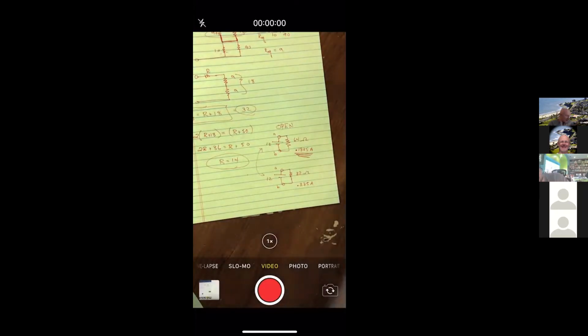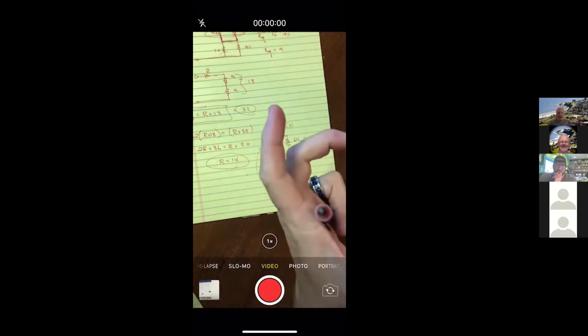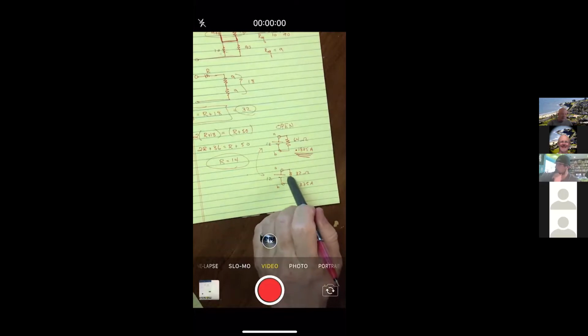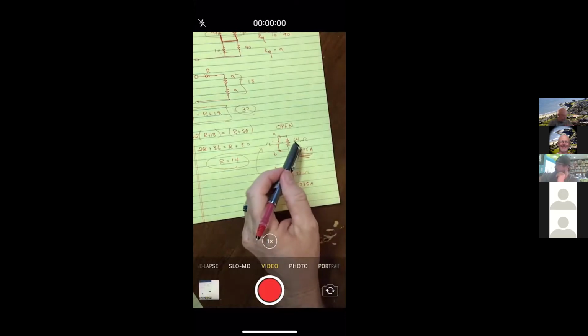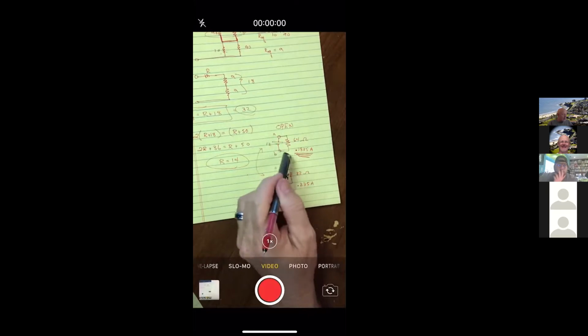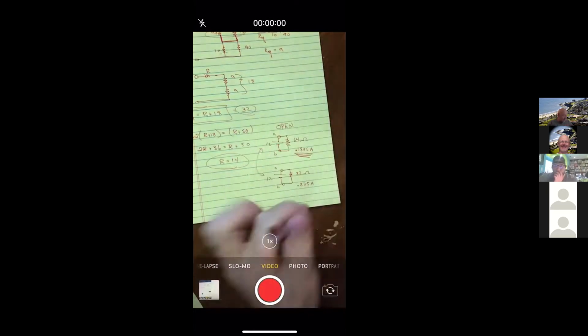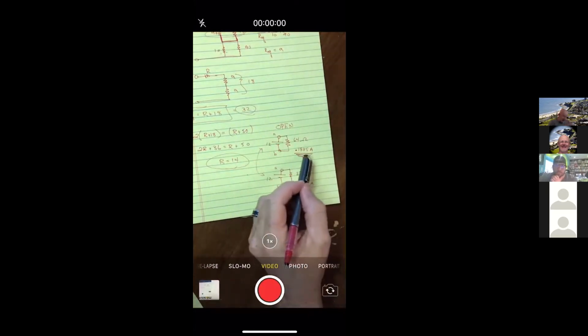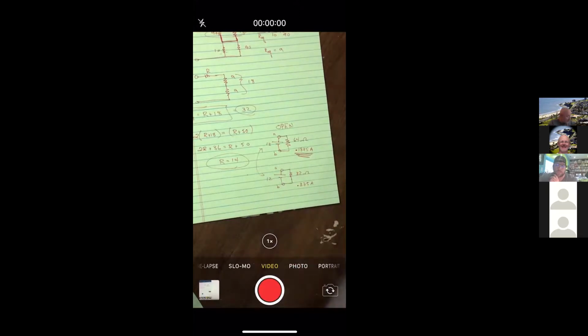But then when nighttime comes along, if they stayed that bright, it would be just too much light in my face as I tried to drive down a dark road. So that little detector up on top of the dashboard doesn't get the light, and that kind of opens the switch, making more resistance. And then the current going to light up my dashboard goes down, and the intensity of the light goes down. And then, of course, at night I have a lower intensity, which again is what I want.